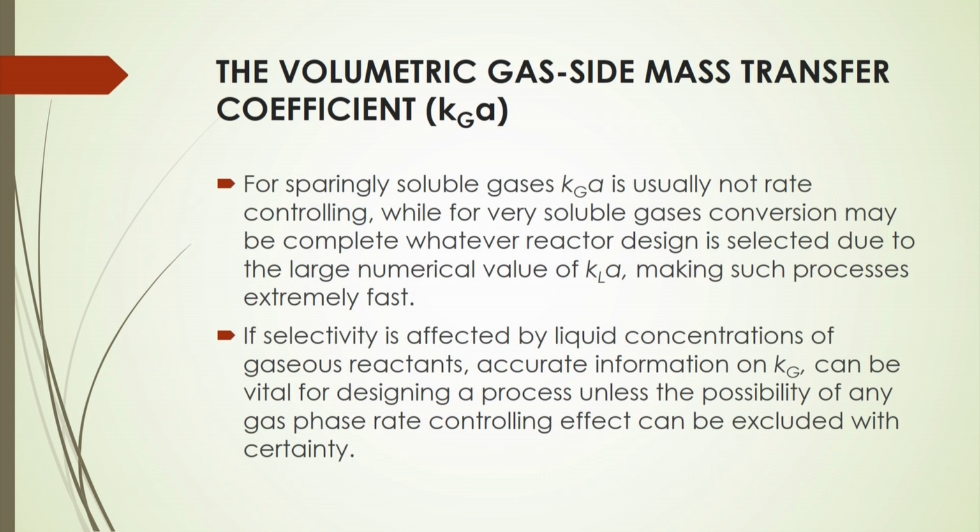Now, if the gases being used are sparingly soluble inside the bed, the gas side is not usually rate controlling. For very soluble gases, conversion may be complete whatever reactor design is selected, due to the large numerical values of KLa, making such processes extremely fast.